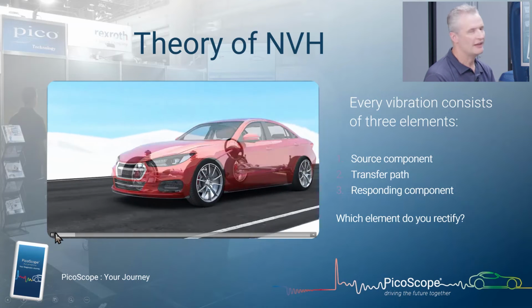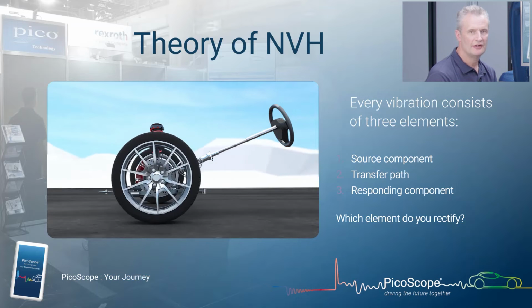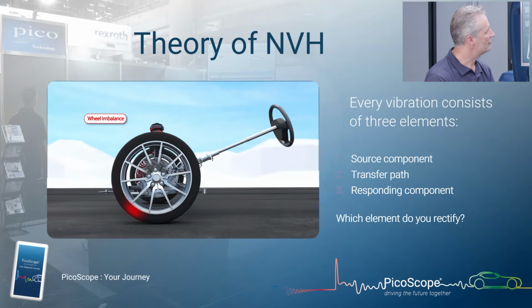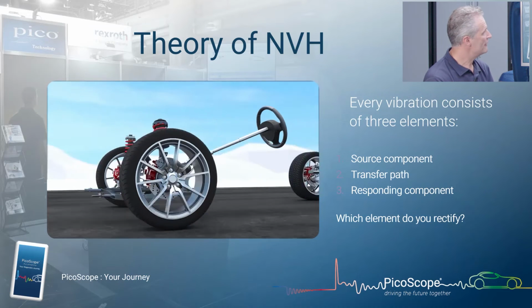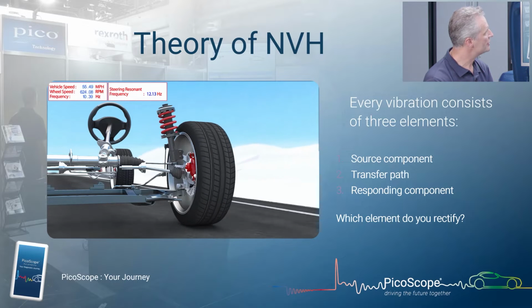Okay, so here is that theory in practice. Imagine here we have an unbalanced road wheel. We have that tendency for the wheel to move outward as the weight reaches the top. There is our imbalance, and ultimately that's going to manifest itself and transfer through the suspension. So we see the vibration there.